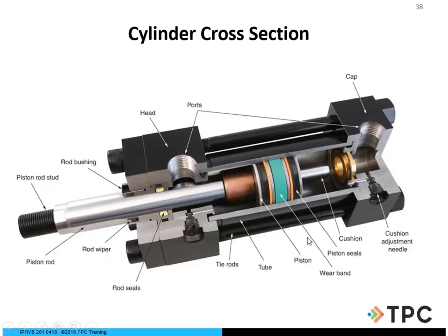And then what do you have? You have leaks. The seals will deteriorate in a short period of time. The reliability of the seals has now decreased quite a bit. And then now we're replacing these packings. And then your boss will say, hey, you just got done doing that a while back. So how come they're still leaking? Well, we didn't look at the compatibility between the hydraulic fluid and the seals we're actually using. So these are critically important aspects of it.